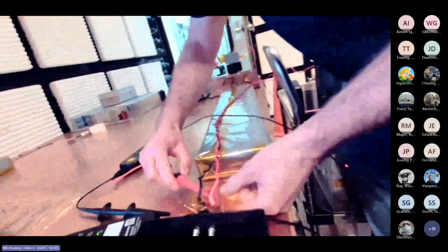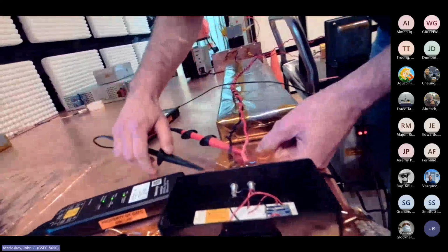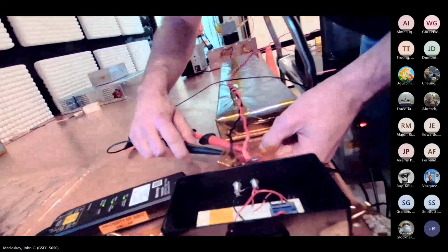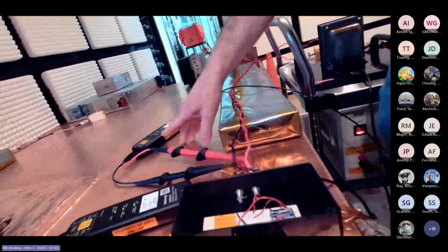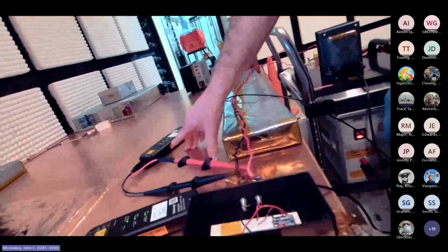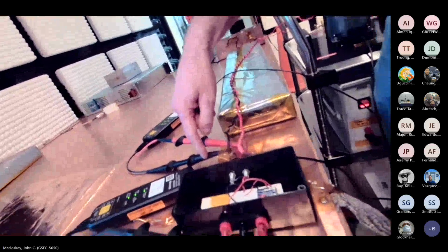Okay, so one of the things we want to look at is the voltage across our input terminals of the EUT to our power feed. So we have this over here. There's this little doodad that we can hook up to these banana terminals that provides a handy thing to clip on with our voltage probe. So again, high impedance differential voltage probe is what you want here,